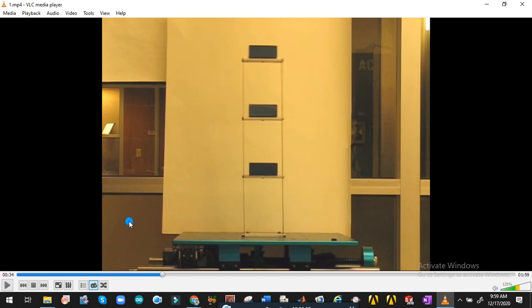Yes, very good question. It depends upon the mode shapes. So that's why we need to find out the mode shapes. The reason is that it may be possible that multiple floors will have the same natural frequency, and they will be vibrating at the same mode shape. But consider that if the system is excited at only one excitation frequency, it will be vibrating only at that particular frequency.